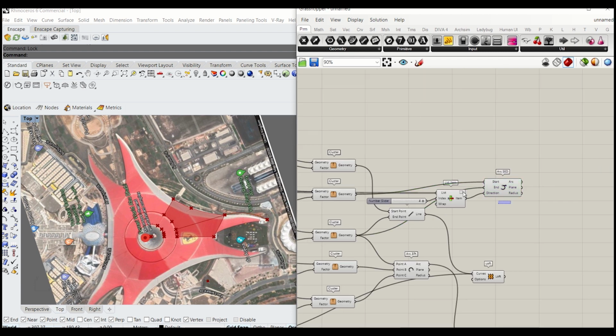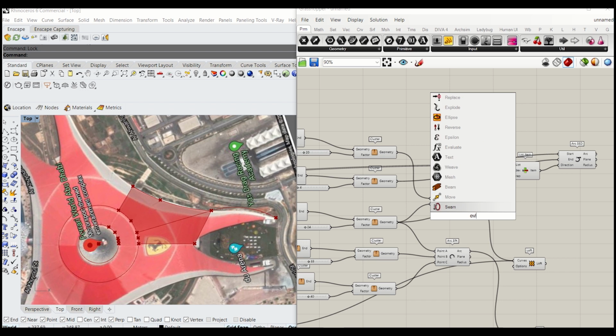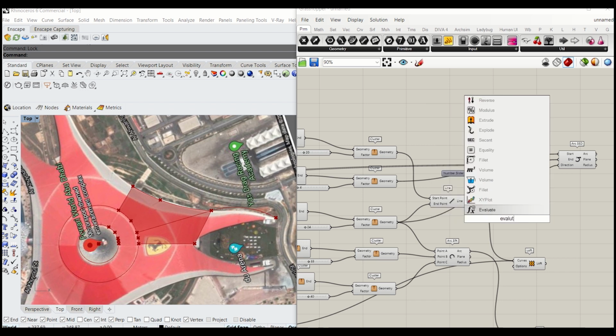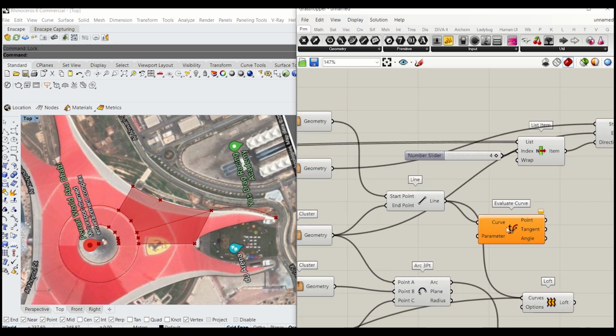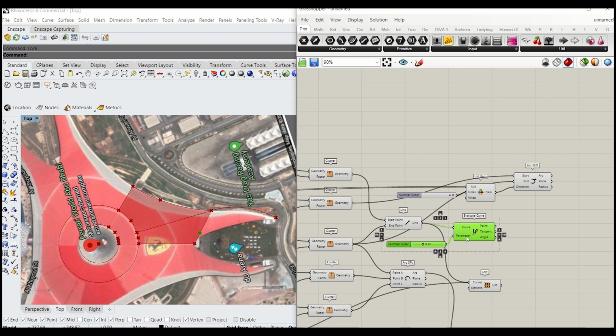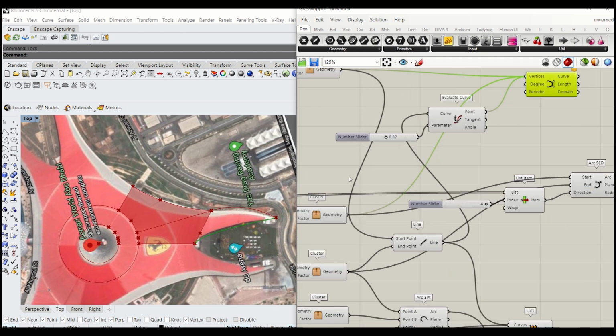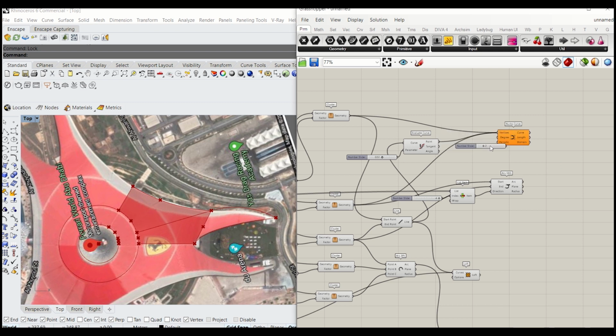And the second that we need to get is we're going to use NURB curve, and that will get a control point from this line there. So I'll do evaluate. Curve goes 0.0021. Parameter connects to there. So if you run it there, it slides up. So that has to sit somewhere around there. We're going to create a NURB curve based on these 3 points. So 1, 2, and 3. So that's been constructed there, and if you move it and roughly position it somewhere around there, I'm going to give 2 for the degree.